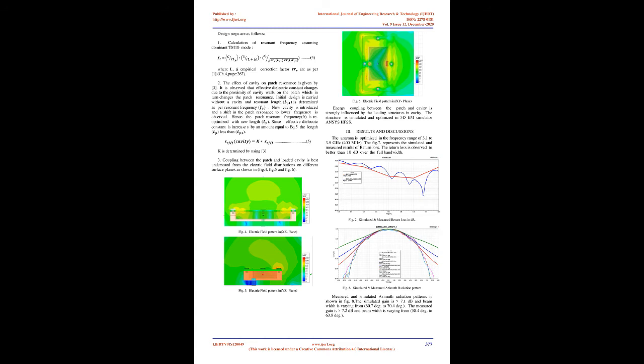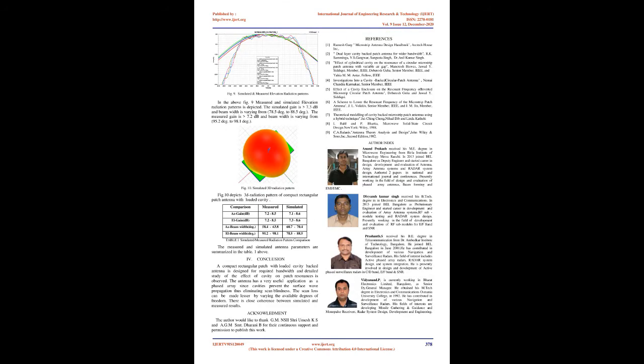Coupling between the patch and loaded cavity is best understood from the electric field distributions on different surface planes, as shown in Figure 4, Figure 5, and Figure 6. Fig 4. Electric field pattern in XZ plane. Fig 5. Electric field pattern in YZ plane. Fig 6. Electric field pattern in XY plane. Energy coupling between the patch and cavity is strongly influenced by the loading structures in the cavity. The structure is simulated and optimized in the 3D simulator HFSS.